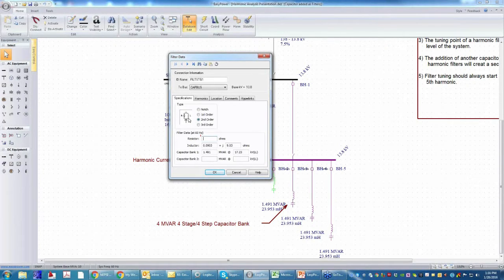And I'm going to show you that in a moment. But in general, it's safe to say that you don't want to decrease the resistance value of a medium voltage filter bank such that the kW losses in that resistor go, say, beyond 30 kW per phase. That's a typical range that I will stop at.